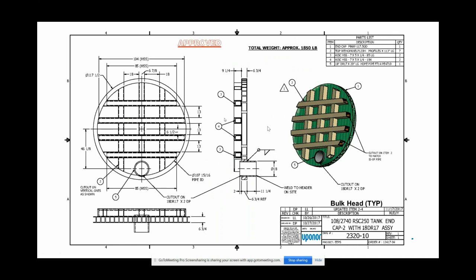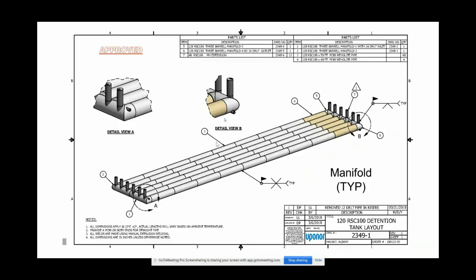This is a good detail of a bulkhead. Bulkhead designs vary depending upon the application. That varies depending on the diameter of the Weholite, the buried depth, and we will do finite element analysis to make sure that enough reinforcement is added to keep the deflection very low.